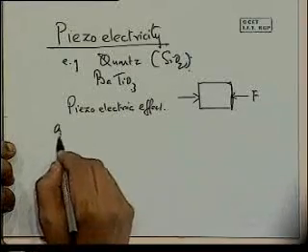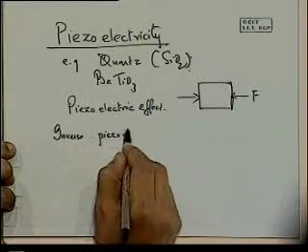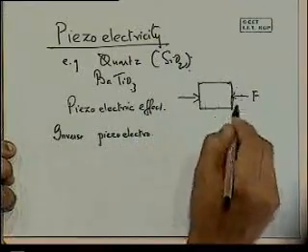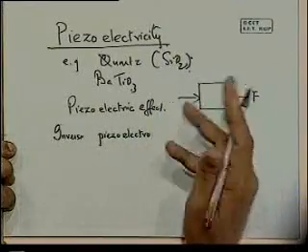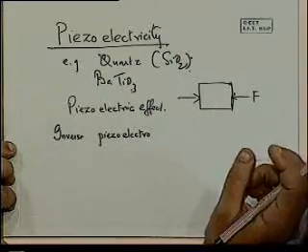You can also have the opposite effect, the inverse piezoelectric effect. Namely, if you apply a field across the crystal, it will change its dimensions. It will either expand or contract. So it's very useful. Basically it's converting electrical energy to mechanical energy, or mechanical energy to electrical energy, one way or the other, depending on what you're doing.